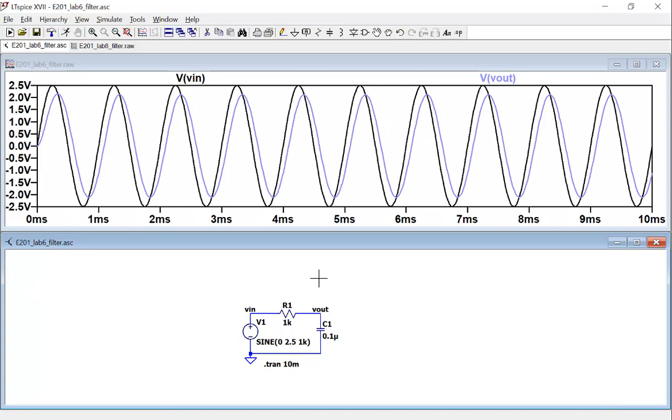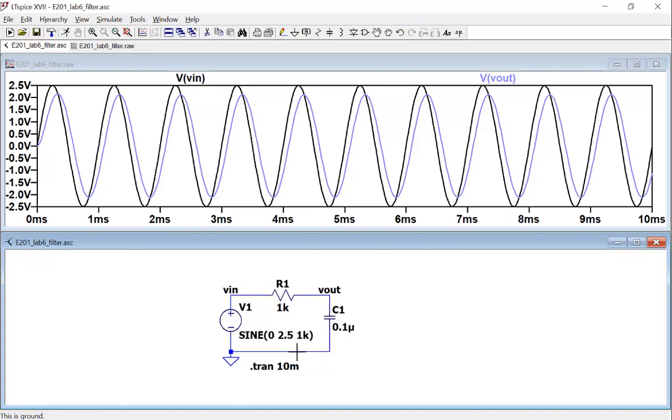So it's being attenuated because this is a low, high pass filter. Is this a low or high pass? Wait. Low pass, right? There's no capacitor to block the DC signal. You've got a DC, it's going to pass the resistor and reach the VL. So there's no way to block the DC. However, if you have a high frequency, it's going to short VL to ground through the capacitor. So it's a low pass filter. So for high frequency, it's going to be attenuated by the filter.